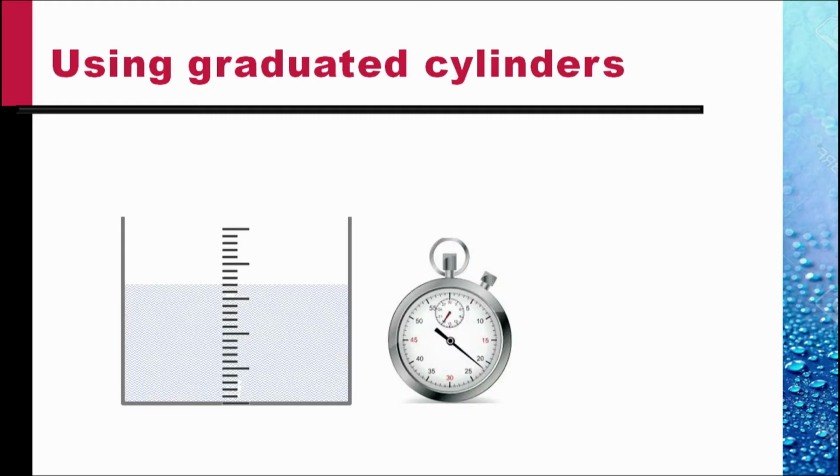Of course, the simplest method of finding flow rate is to let the fluid or a liquid flow into a jar which is calibrated. We measure the amount of volume collected in a given amount of time as measured on a stopwatch, and from these we calculate the flow rate. This is a typical method you use in the undergraduate labs, but in industry, which are automated, this would hardly be desirable.